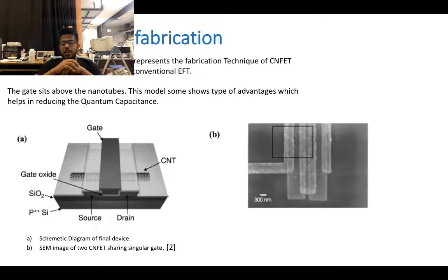In these slides, there are many types of ways of fabricating carbon nanotube based FET. In this case, we have tried to duplicate the normal FET or MOSFET so that the structure made is comparable to the present technology of MOSFET, and their comparison can be done. Here you can see that the gate actually sits over the carbon nanotube. You can have the gate below the carbon nanotube; the properties won't change at all.